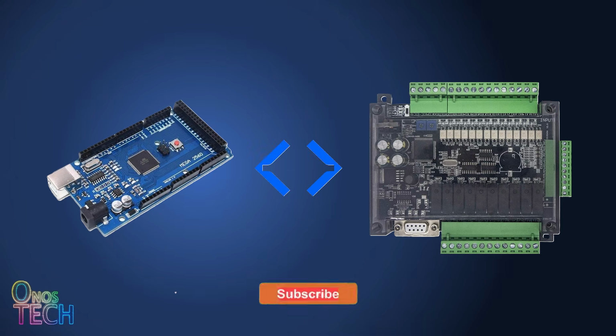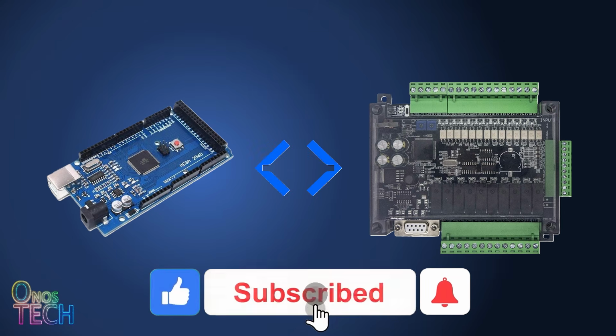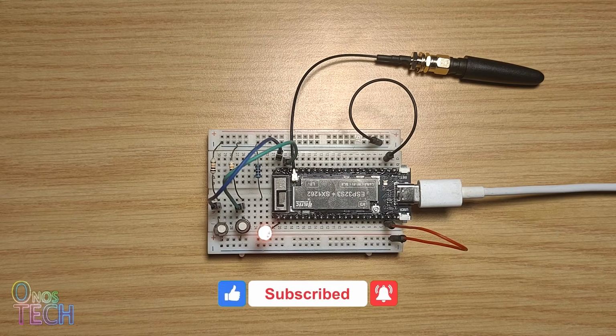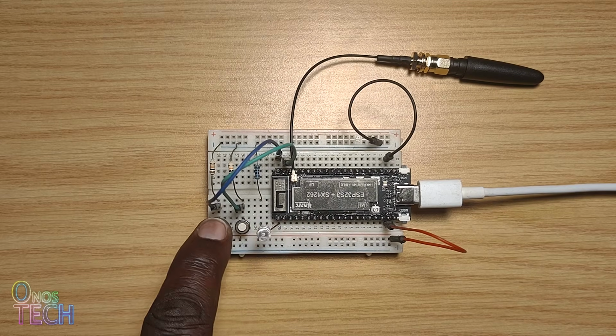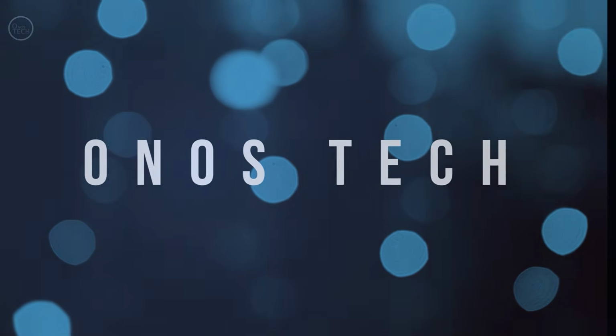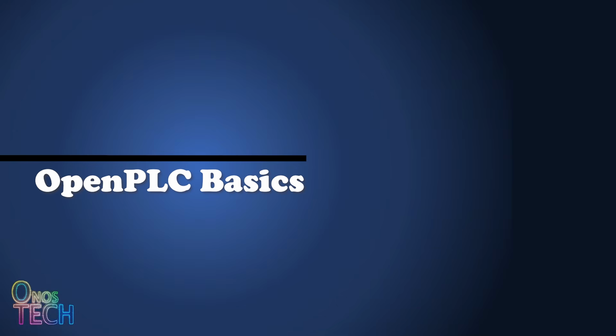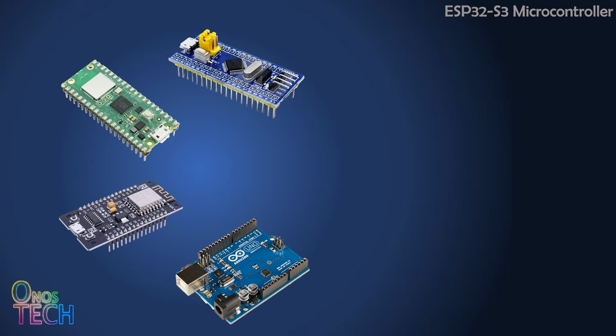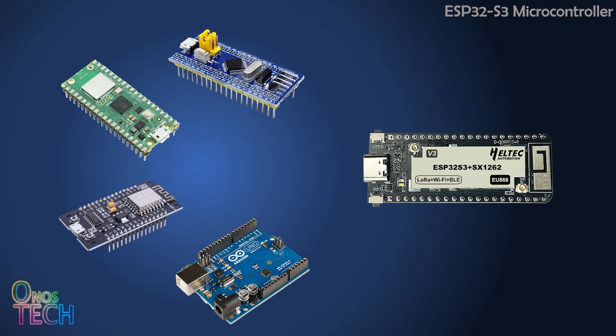The ability to run on everything from Arduino boards to industrial controllers like the FX3U is what makes the OpenPLC so powerful. In this series, we will build our system using the ESP32S3 with an integrated LoRa chip. You can follow this series using any microcontroller board of your choice. However, we will be using this version of ESP32 because of its built-in LoRa radio support, which we will dive